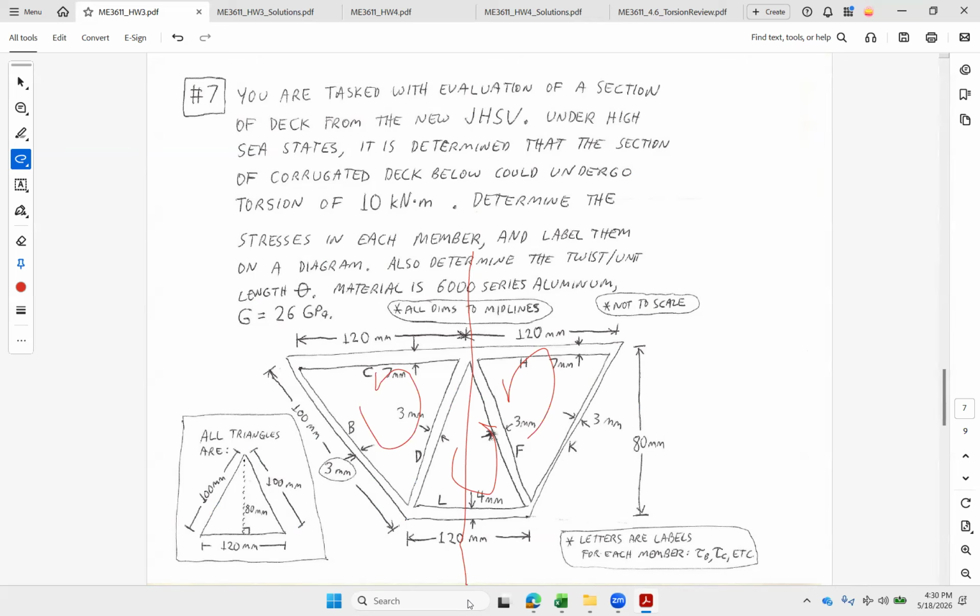And we'll get what's called a skew symmetry. So if it's going down and to the right on B, it's going to be going up and to the right on K. Also, Q1 and Q3 will have to be the same. Q2 equals Q2, so we're covered on this middle one across the symmetry line, but Q1 and Q3 will also have the same magnitude. We'll see how those work out.